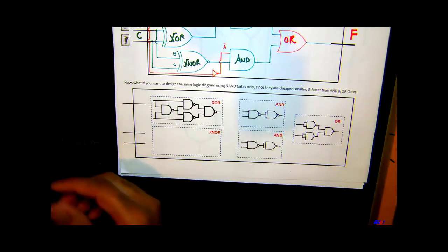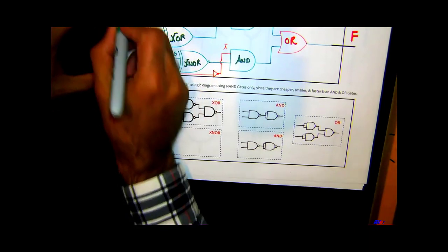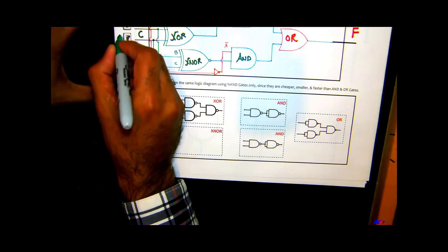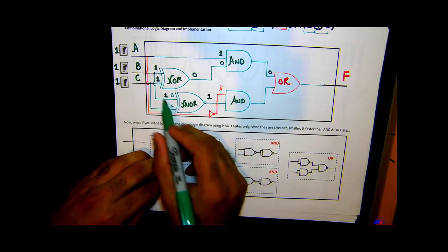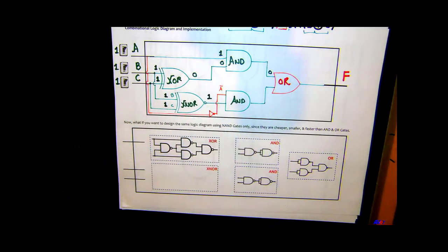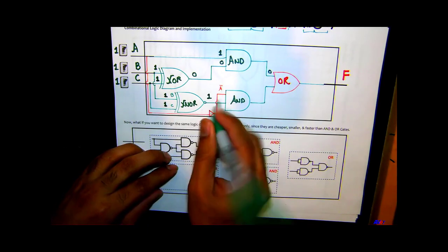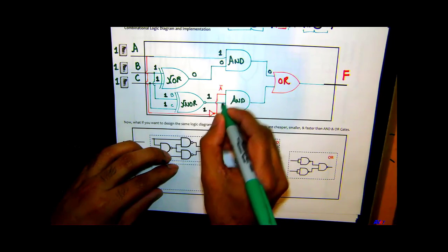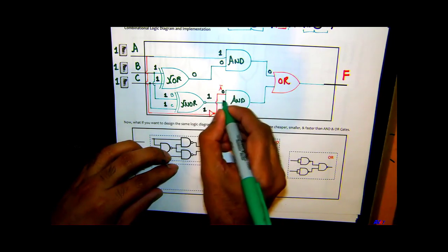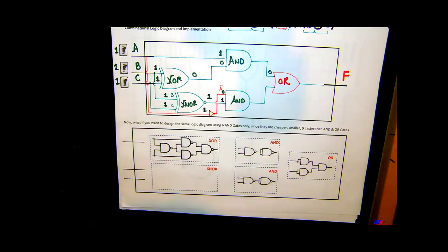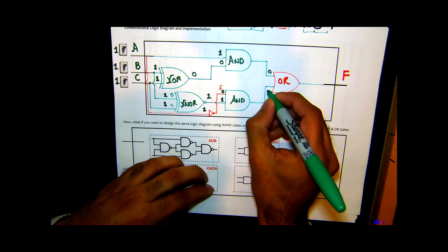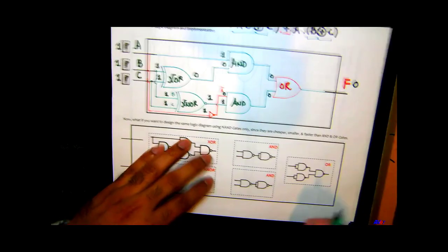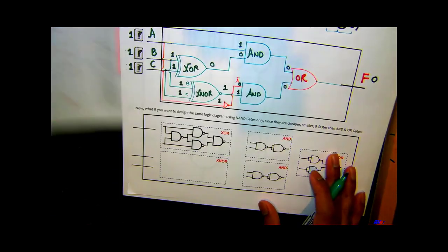Maybe we can go with, again, because the position of the switches is set to 1. So say we got 1 here, and 1 here. Okay, so 1, 1 going through an exclusive NOR gate is 1. And then this is A, right? So A was 1. Going through an inverter, it becomes what? 0, right? 0 and this 1. 0, 1 going through an AND gate is going to be what? 0, right? 0, 0 going through an OR gate will give you 0.